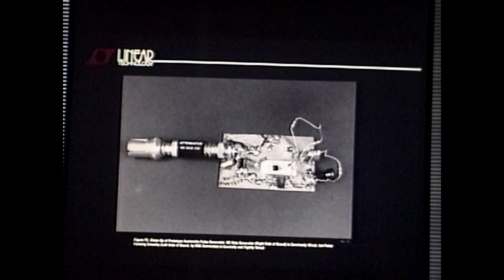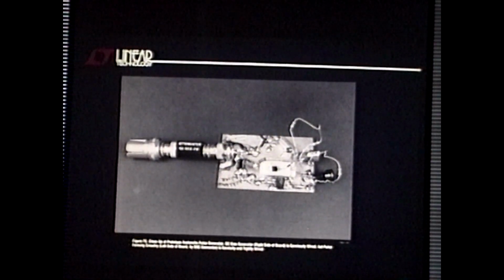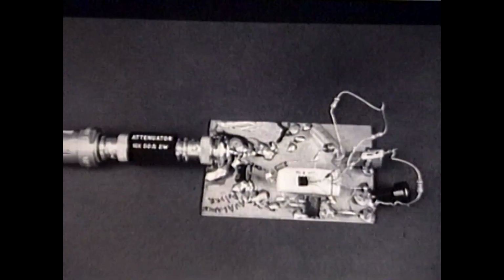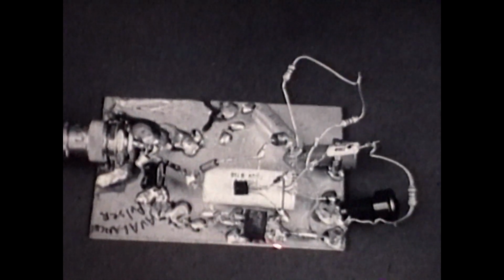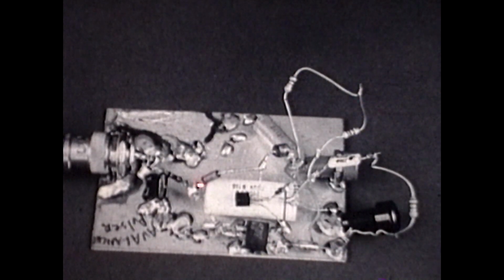Okay, let's take a look at this close-up view of a prototype of the avalanche pulse generator. We're talking about something that makes waveforms in hundreds of picoseconds. Look at this breadboard. See here? That's the DC to DC converter. I'm not going to waste 5 minutes breadboarding that. It's a waste of time. What you can probably see better in the handout is the attention that went into the layout in the business end of this thing, which is the avalancher. This can be ugly. But this here, that's got to be bulletproof, and that's where you spend the time.